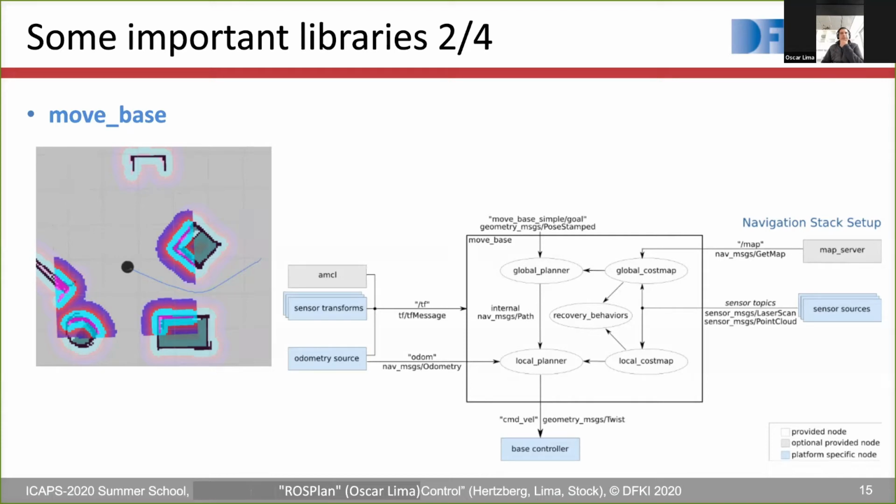So this is a bunch of things that are happening in the background for you automatically when you call MoveBase. And one of them is the localization algorithm, which is here handled by the particle filter. This is the robotics algorithm that tries to match the laser scanners of the robot with a known map. And then you can know the XY position of the robot in the environment.